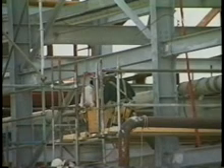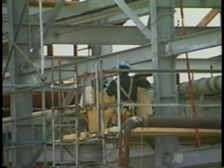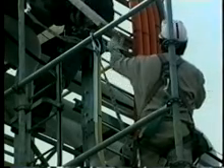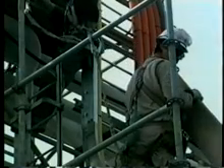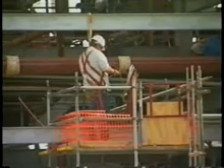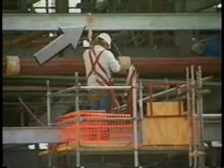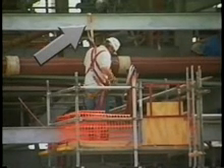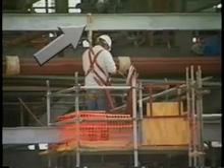On Beck jobs, fall protection is required at a height of 6 feet or more, including scaffolding. There are no exceptions. Both guardrails and the personal fall arrest system are required on self-contained adjustable suspension scaffolds. When a fall arrest system is used on a scaffold, it must be properly secured to an anchorage that is independent of the scaffold, so that the worker will be protected if the scaffold falls.